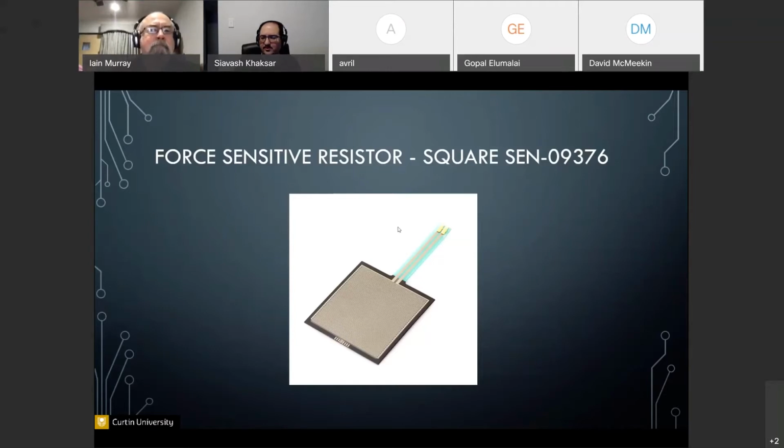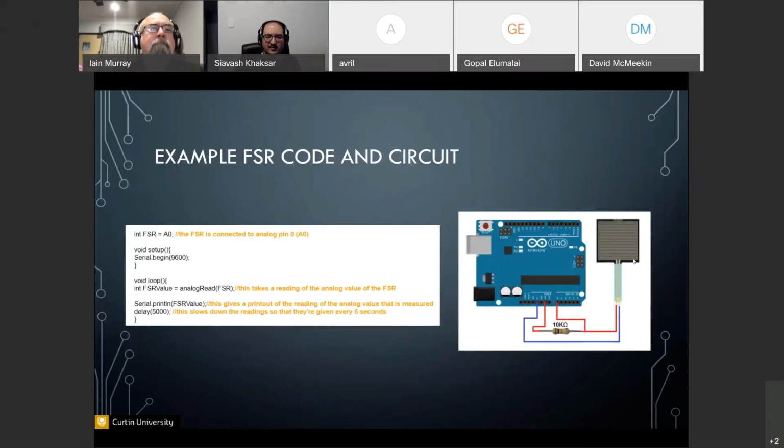The picture you're seeing here is a pressure sensor. If you put pressure on that pressure pad, also called an FSR, the resistance of it will change. The way this one is read, as you can see, is a very simple example code. We have our main setup, and we read the pin that's connected to one of those headers, and the other header goes to the ground.